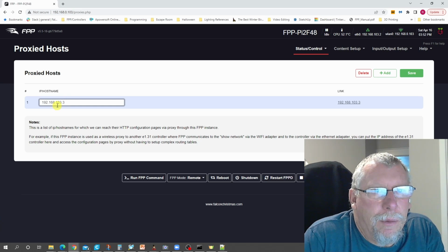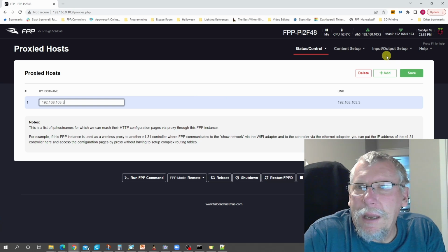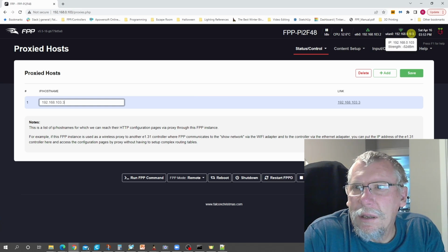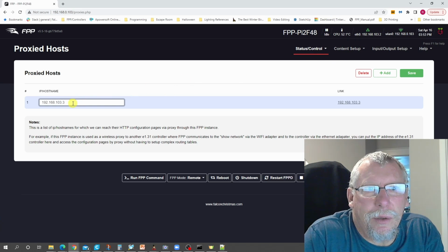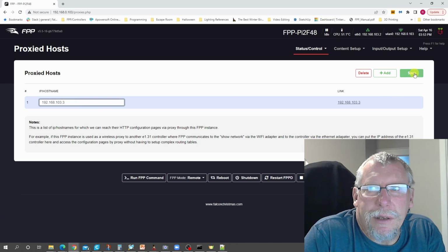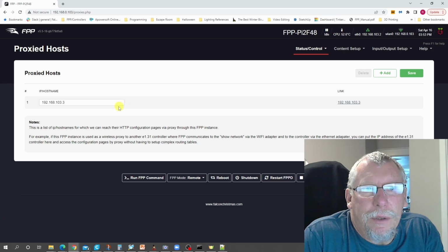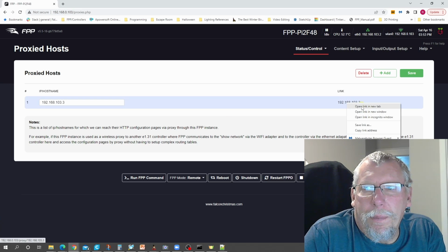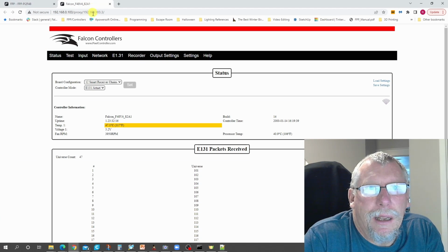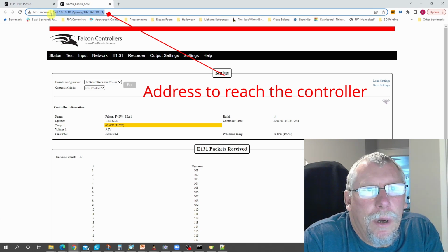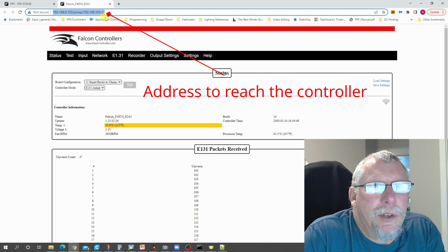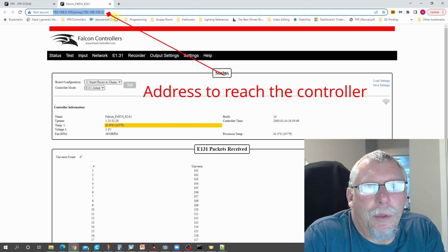192.168.103.3. And if you remember how I did the numbering, if you look at the IP address of here, it ends in 103, so the device is going to be on a 103.2, and then I just do 103.3, and it makes it a little bit easier to follow. And then once that's set, then you can get to the device by clicking on it. And if you see, you've got access to it now, but you have a weird IP address. You can't just type in 192.168.103.3, which is the address of this controller. You have to go through this proxy address.